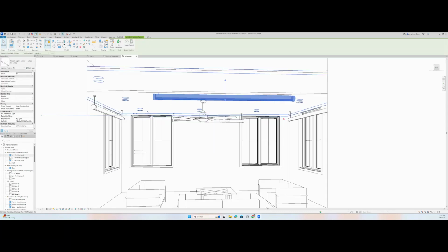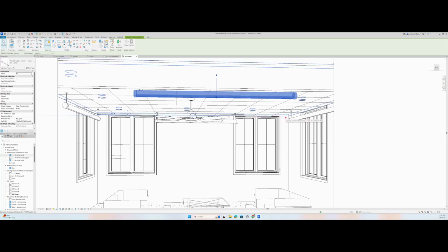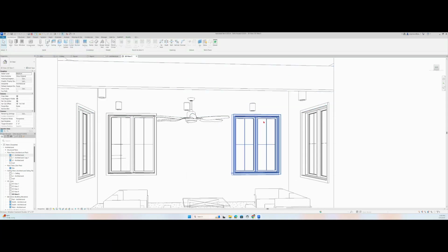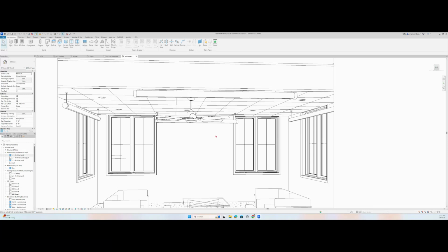And something that they did new in Revit is that when you select the ceiling and you delete, some of the items stay, like those recessed cans, and even the ceiling, they're not hosted anymore. But my hanging lamps, they're gone, right? So be careful with those things.